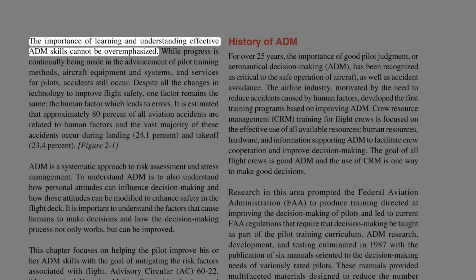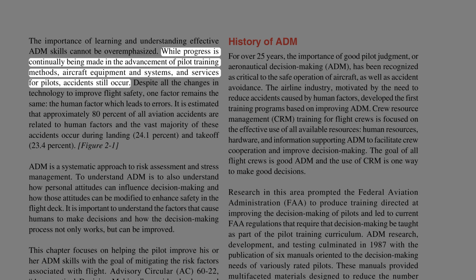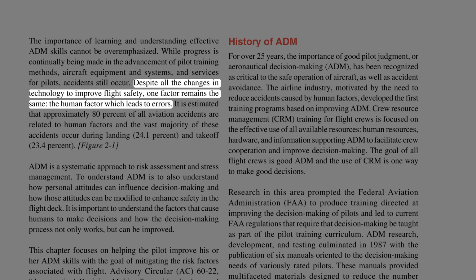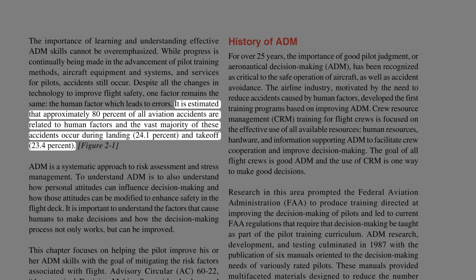The importance of learning and understanding effective ADM skills cannot be overemphasized. While progress is continually being made in the advancement of pilot training methods, aircraft equipment and systems, and services for pilots, accidents still occur. Despite all the changes in technology to improve flight safety, one factor remains the same: the human factor, which leads to errors. It is estimated that approximately 80% of all aviation accidents are related to human factors, and the vast majority of these accidents occur during landing, 24.1%, and takeoff, 23.4%.